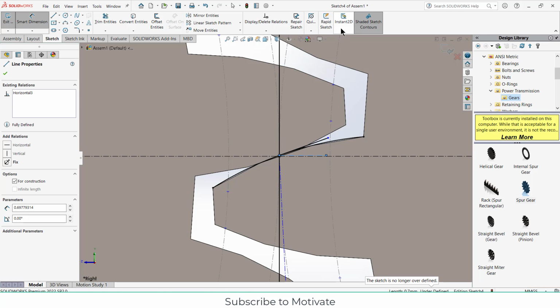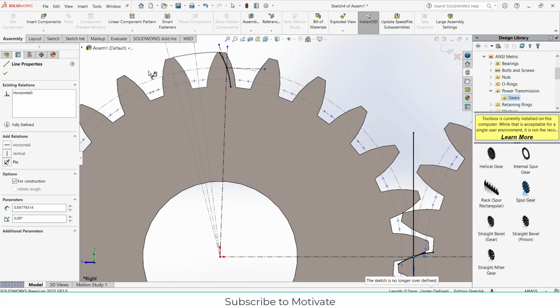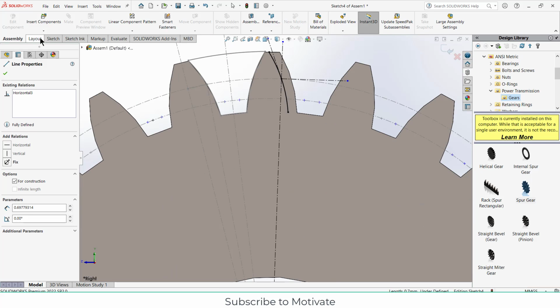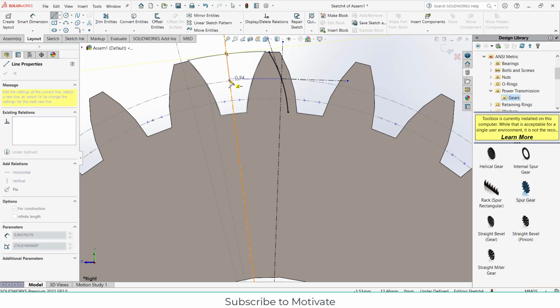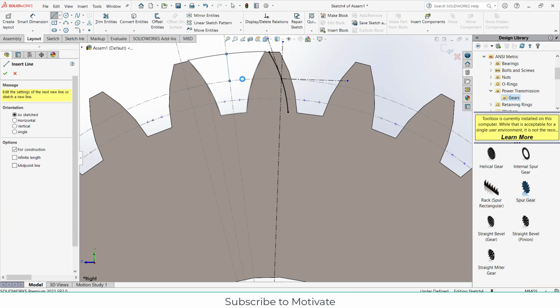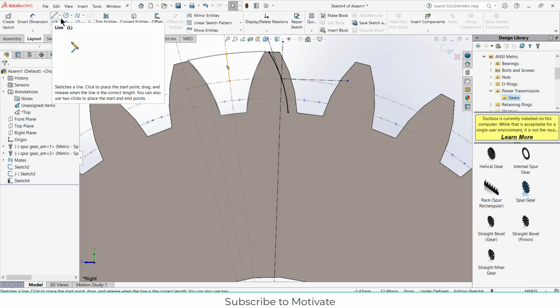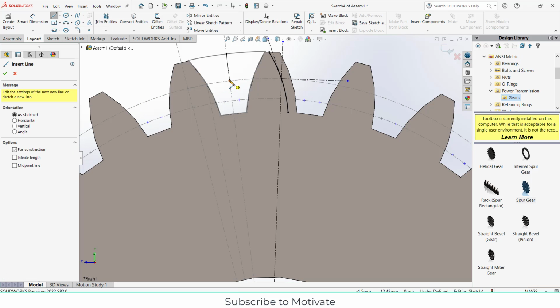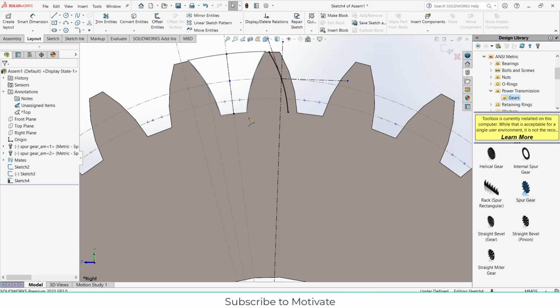Okay, now the next term is addendum. So what is an addendum? Addendum is the distance from the top of the tooth to the pitch circle. So this line is called the addendum. Now, what is dedendum? Dedendum is from the pitch circle to this line at the bottom of the gear. It is called the dedendum.